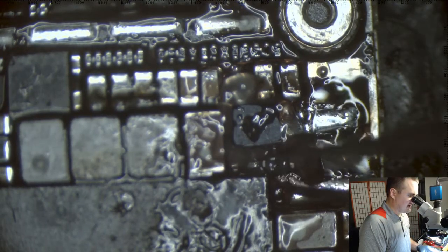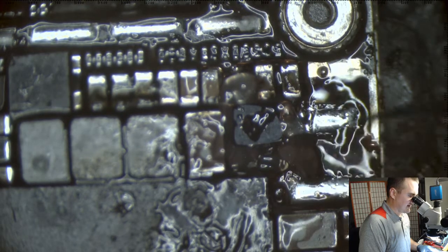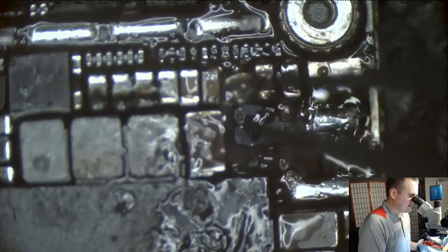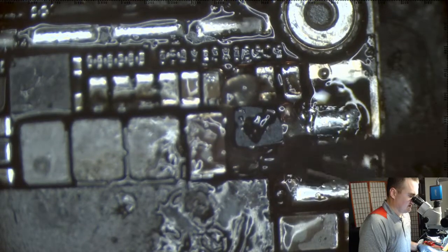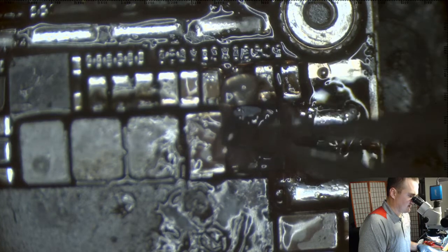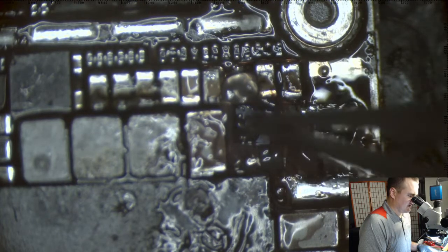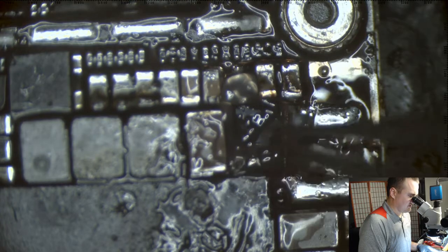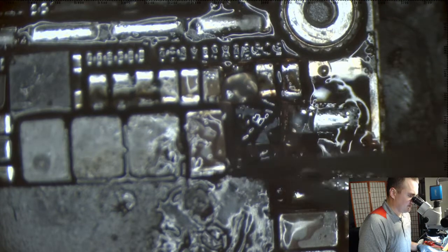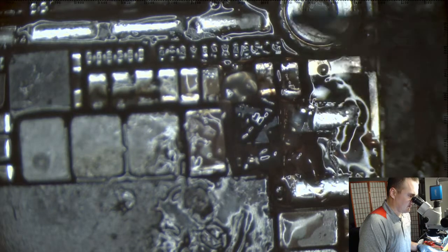So this diode's got a little line on the side it's blocking from. So current can pass that way. It can't go this way. The reason this diode's even here is because this is the feed side, and it takes the very same circuit and turns it into the output side. So it goes in here and it comes out this side at 19 volts. We got 4 volts, 19 to 22 volts. You don't want to be sending 19 to 22 volts back all the way through this coil up into your main power rail. Don't do it.